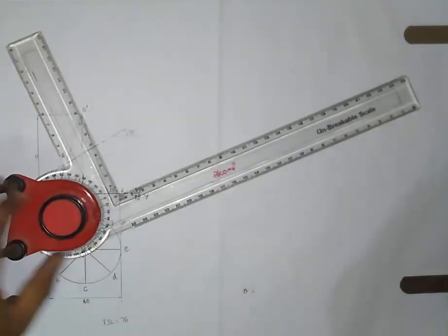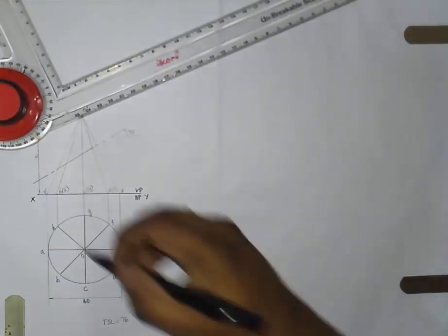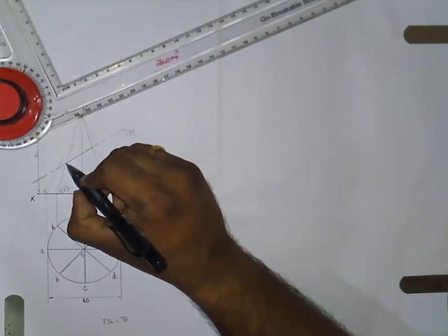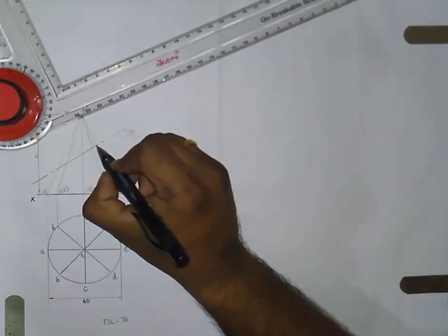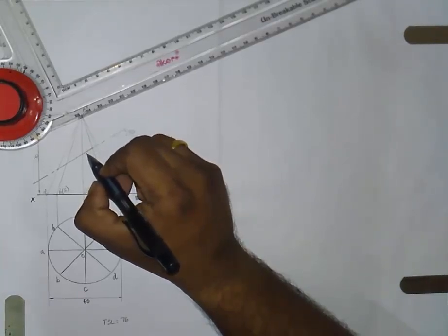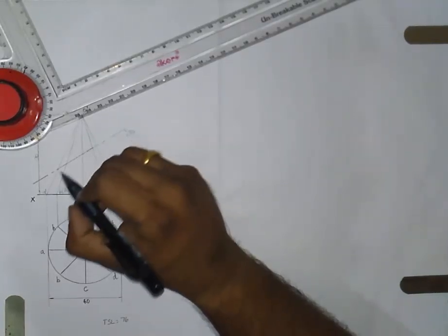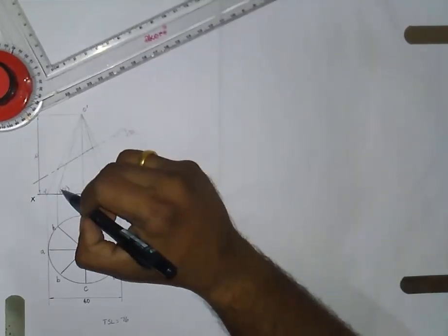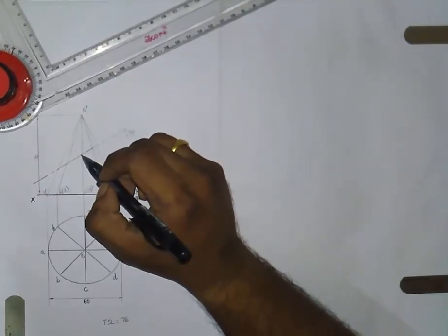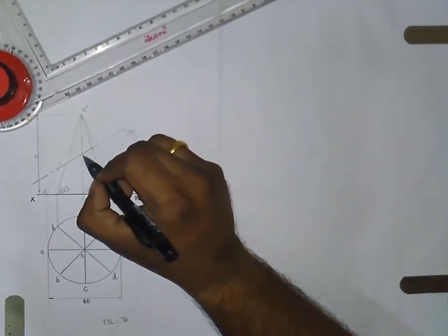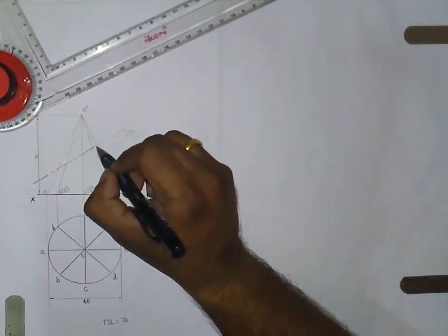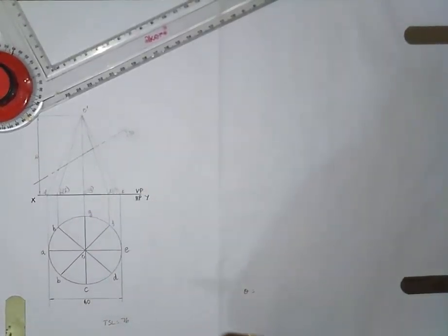Now you have to mark all the cutting points. Here the cutting plane cuts the longer edges at 1, 2, 3, 4, 5 places. Now you have to count the number of cutting points. Here there is only one edge, so one cutting point will come. Here OB and OH, there are two cutting longer edges, so here two cutting points. Here two cutting points. Here only one edge is there, so here also one cutting point will come. So 2 plus 2 plus 1 plus 1, totally 8 cutting points you will have.